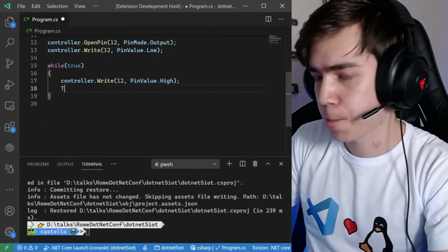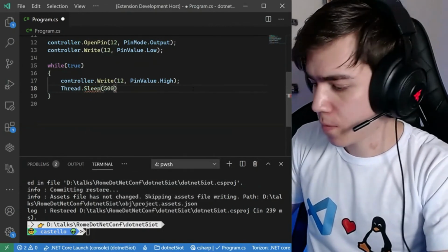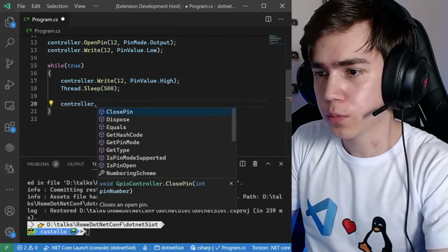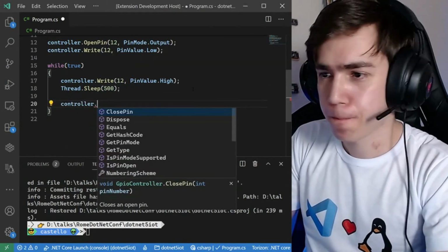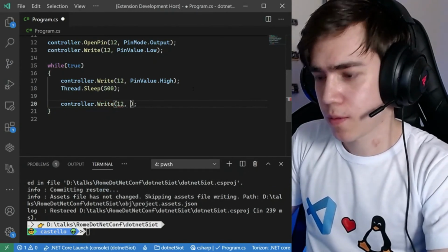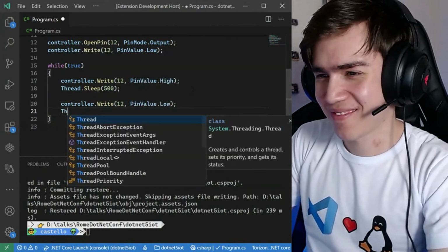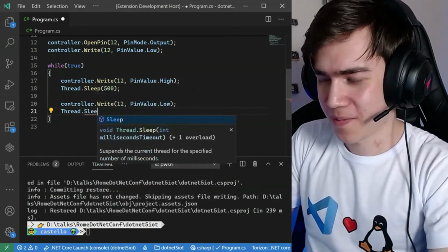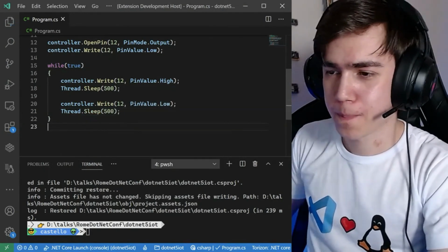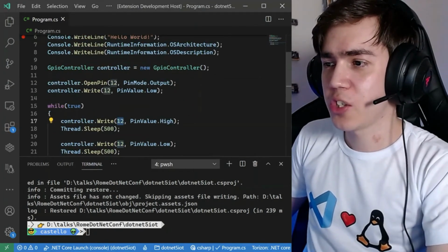Yeah, and a point is that pin numbers and this kind of information usually you need to get from datasheets. So even if we are doing high-level development, at some point we need to deal with the hardware. We need to do what the hardware guys do and go read some documentation. But usually it's not that hard to find this information. Yeah, so the LED is connected on pin 20, right? From GPIO controller 0.